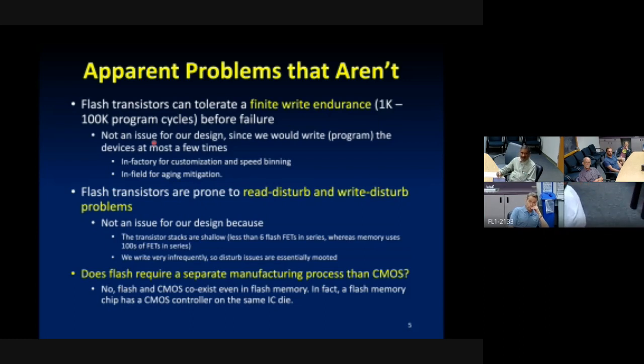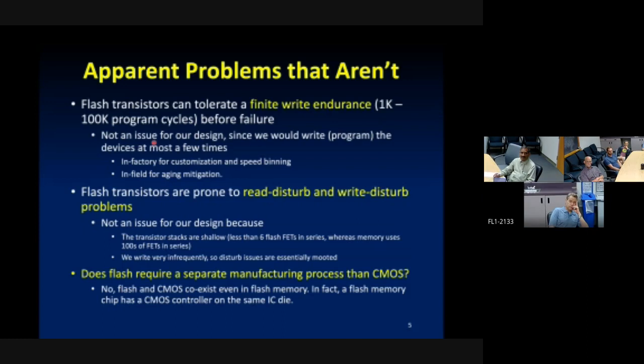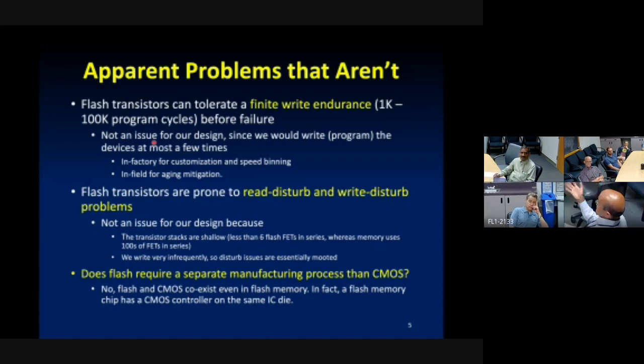The other is the memory folks have this standard problem, which is something called read disturb and write disturb for memories, which basically alters the state of cells when you read or write other cells. Again, this is not a problem in our design because we write very infrequently. And also, the transistor stacks in our design are very shallow compared to flash memory. So all of this reduces or diminishes or eliminates the problems that traditionally are faced by the flash-based memories, right? Because we're not doing memory, we're doing logic designs and analog designs.